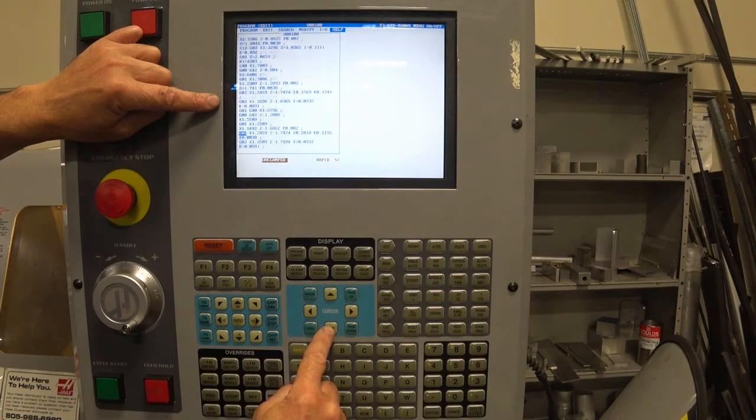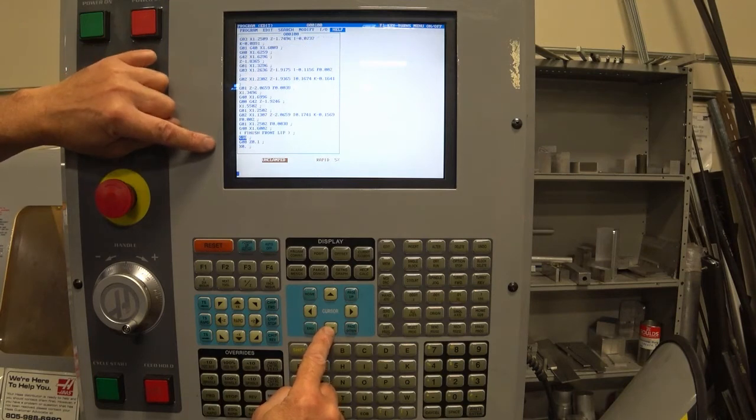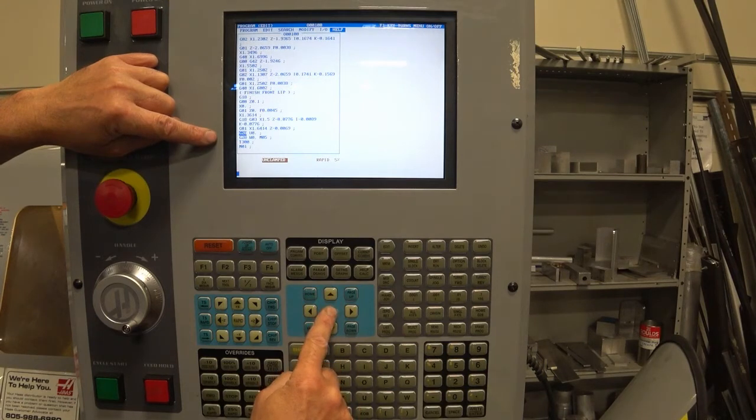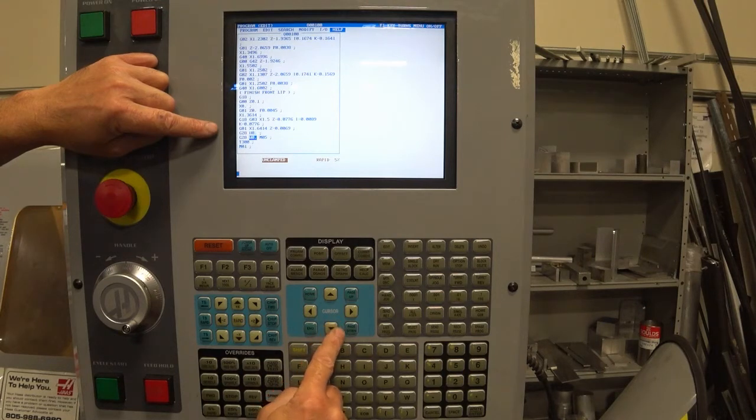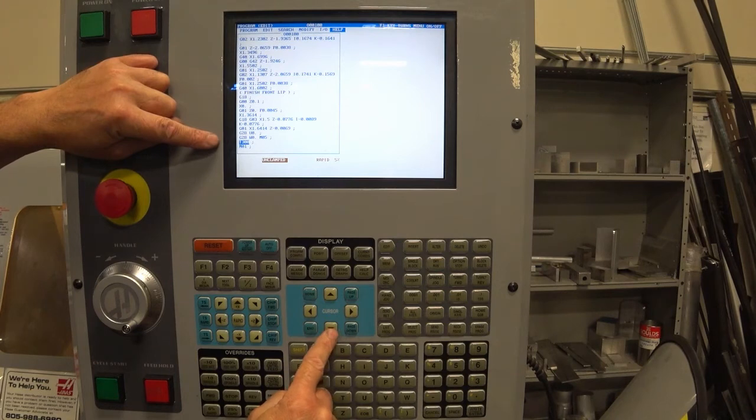Soon you'll see the G28 command. This commands the movement of home for the tool, and it's an incremental movement using the U and W. On the lathe there is not a G91 command. You use G28 followed by a U or a W. If you think of X, Y, Z, U, V, W, you will understand the relationship of the U to X and the W to Z.